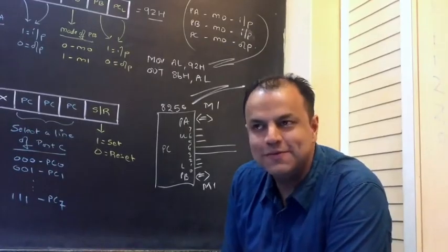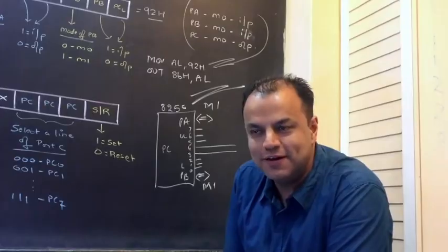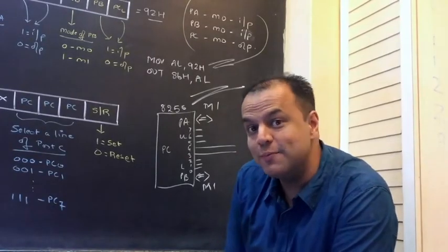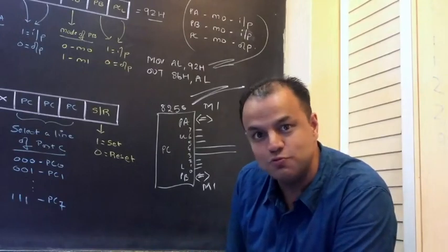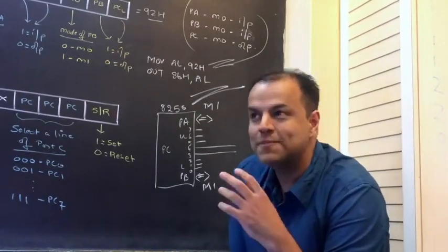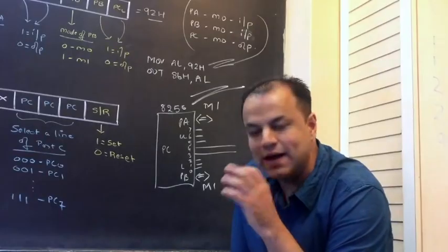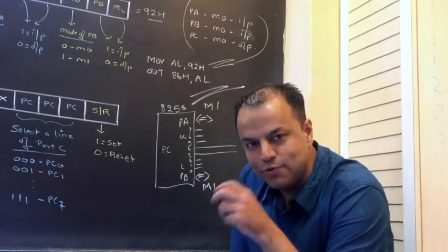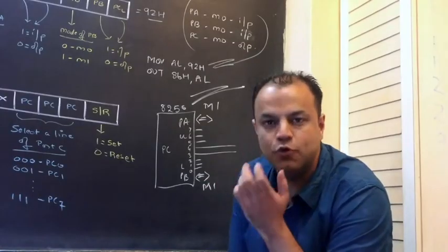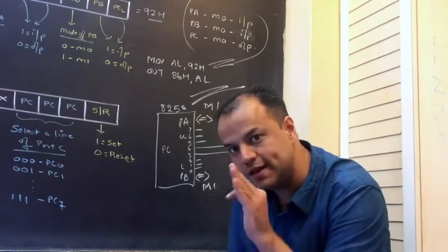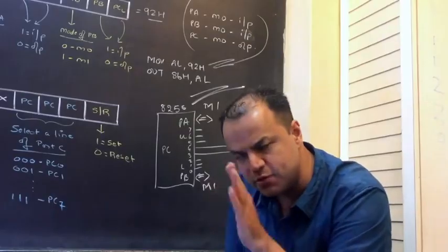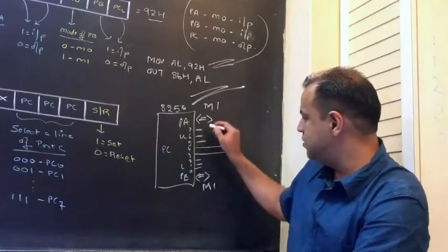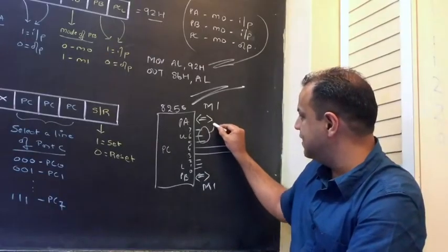I know, don't worry. I told you 4 because you would be wondering, if I had told you it takes only 3 lines, what happens to that 4th line, because we say half goes to port A, half goes to port B. So in the next video, I'm going to show you handshaking in detail. You'll come to know that to do handshaking, any port requires only 3 lines from port C. It needs 4 lines altogether, but from port C, it takes only 3 lines. The 4th line is already available with 8255. Anyway, the point is, port A and port B will take 3 lines of port C.